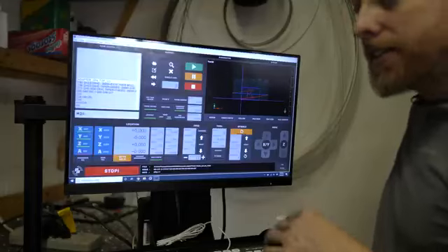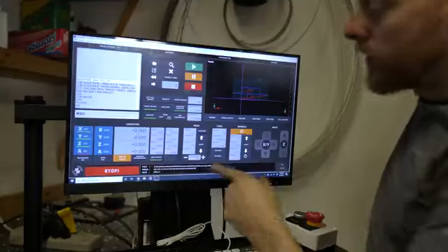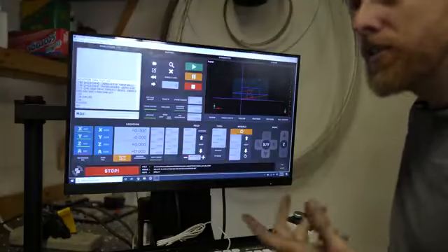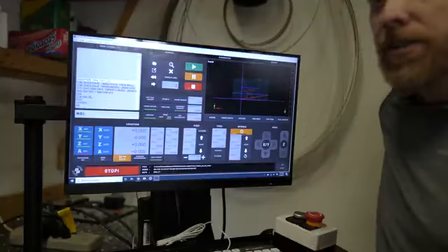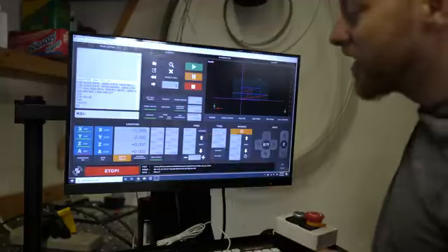For example, if I have probed the top of my workpiece when it's in the vise, and I know that's the top, and I open my G-code and I say, well, my Z minimum is, you know, about 5/8 of an inch down, and my part's only sticking out of my vise 1/2 inch, I'm going to run into my vise. So it's a good double check to use. So I actually have started using those.